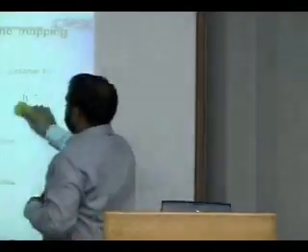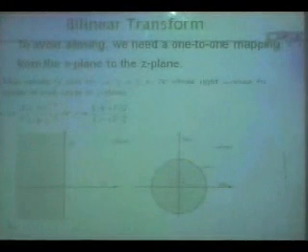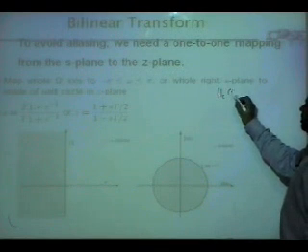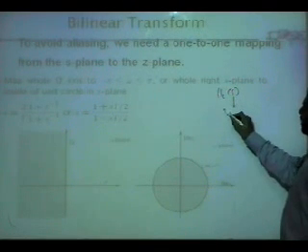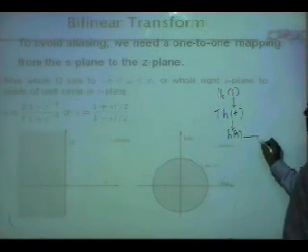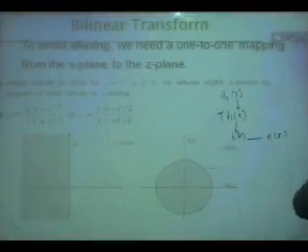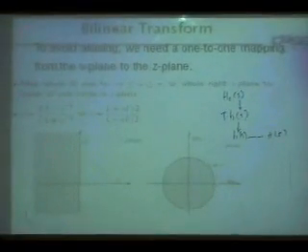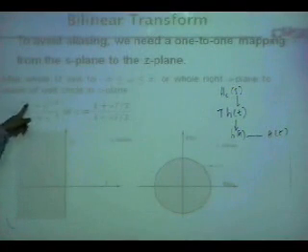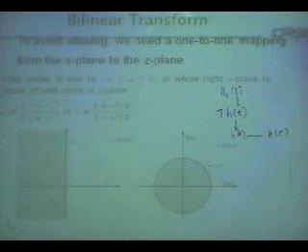And so let's now see what this transformation is. In this transformation, remember you started with HC of S and you converted it to H of T, then you discretized it and took the Z transform. These are the steps you went through to design an IIR filter. In bilinear transformation, you say, no, I will replace S with this complex function: 2 over capital T, 1 minus Z inverse over 1 plus Z inverse. So every S is replaced by this expression.